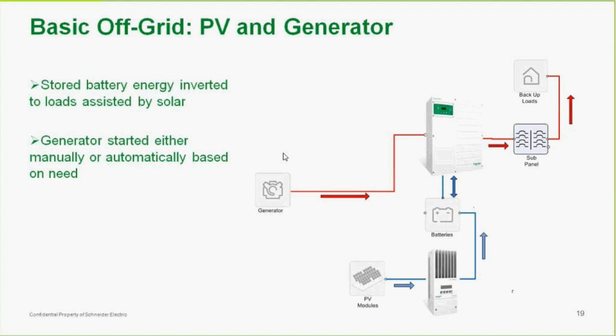Many of you may have heard that term, and some of you may know what it means. Basically, the term coupling means tying something together on a bus. So here, we see the generator, the inverter, and the loads tied together on this AC bus. And we see the PV, charge controller, and batteries and the inverter tied together on the DC side.